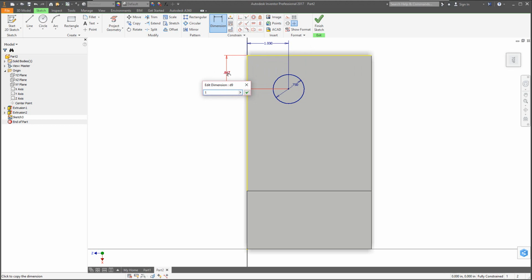And the only reason you want to position it centered or lay it out like you would a drawing, because later on when you learn how to create drawings, the 2-dimensional side of this, those dimensions will appear how you left them in most cases. So it saves some time having to move them, and you could pretty much just say drop in the dimensions, and there's a lot less work to have to do.